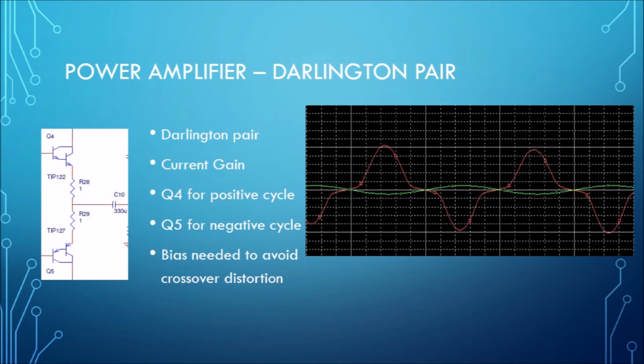And one more word about connecting the Darlingtons to the load resistance. Here we used a very large capacitor compared to all of our other ones. This is because here the equivalent resistance seen by the capacitor is lowest. It only sees the couple ohms from the Darlingtons and the load, which is 8 ohms. This drives the threshold frequency very low unless we compensate by using a higher capacitor.